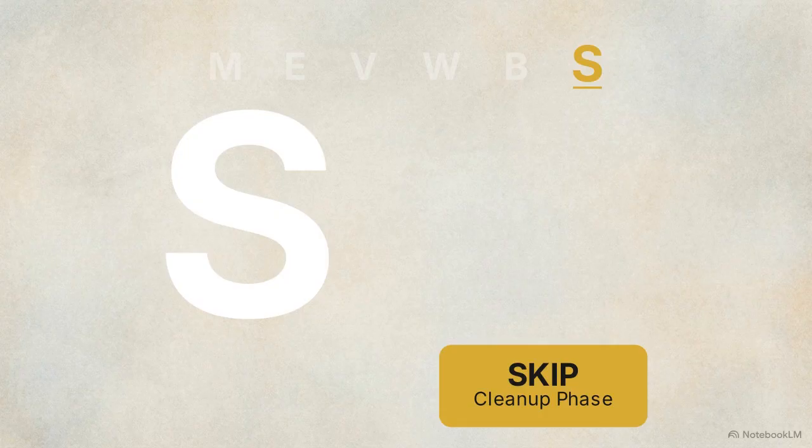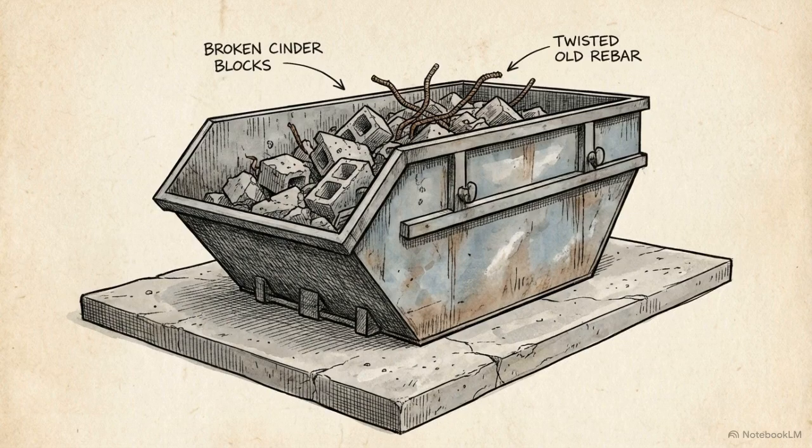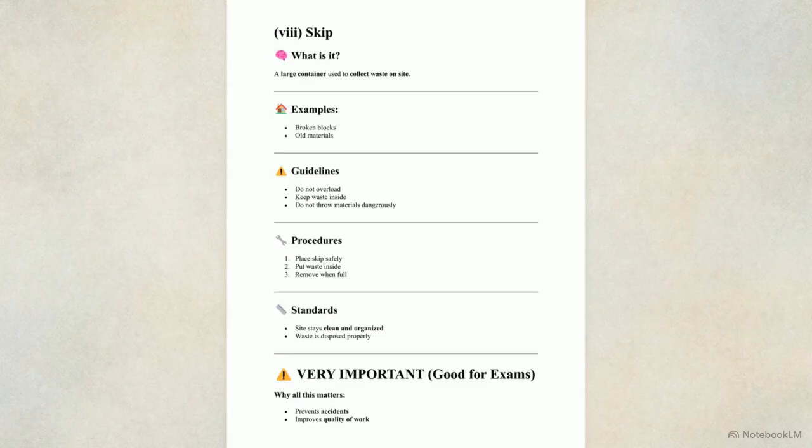Finally, we reach S for skip. This is the large open-topped container used in the final phase of the equipment cycle, site cleanup, specifically for collecting broken blocks and old materials. There are strict parameters for safe waste disposal here. The skip must be placed safely on flat ground, it cannot be overloaded, and you must place materials directly inside. Never throw heavy debris into the skip from a distance.